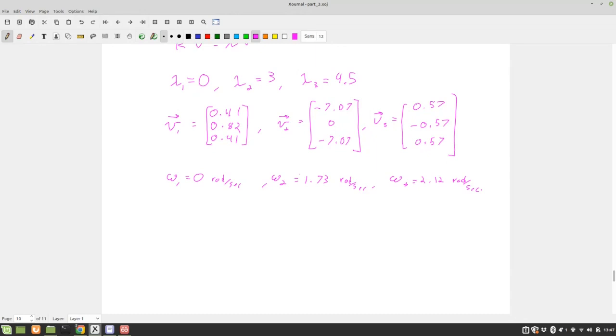Yeah, it's got to be normalized, right, by that M inverse. But remember, the middle value of m is double the outside values of m. And so if you look at that, you'll see what's going to happen. So now we need to solve for our mode shapes. So u vector is equal to m negative 1/2 v vector, right? U is your mode shape. V is your eigenvector. So what's your first mode shape?